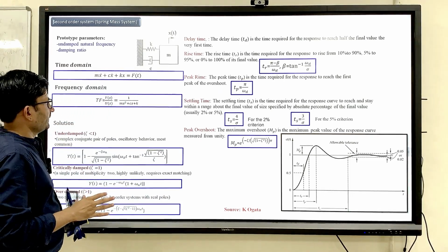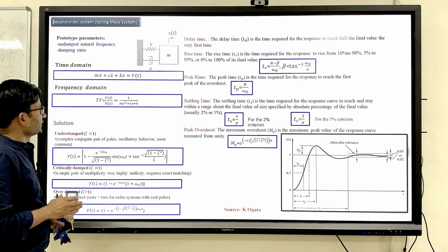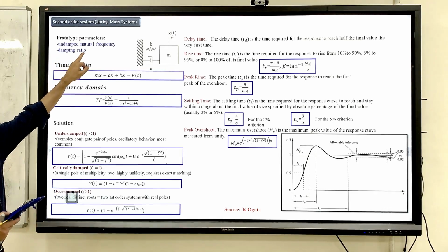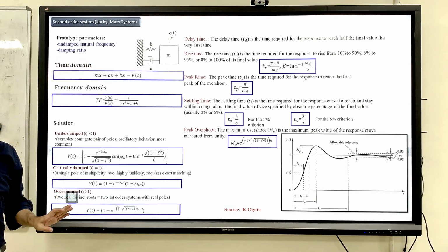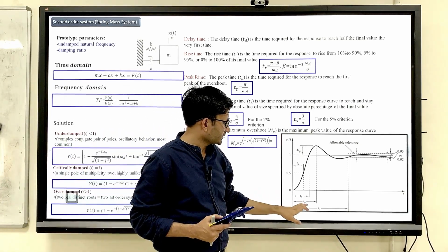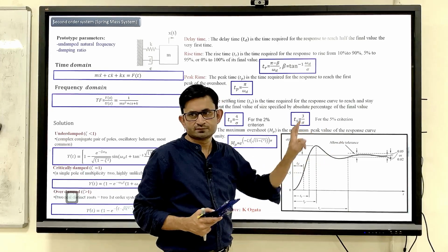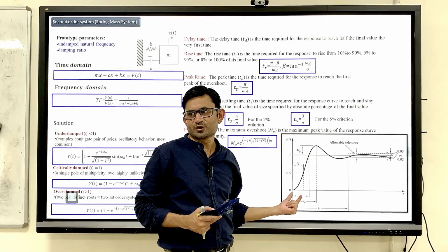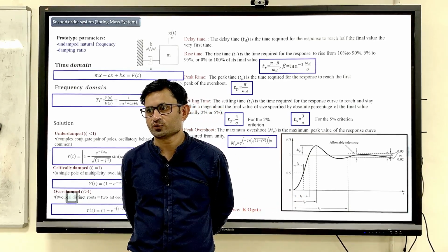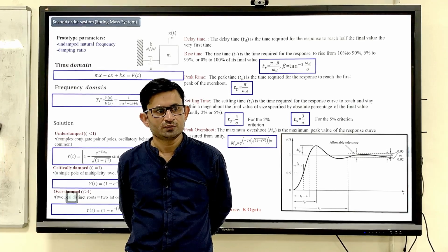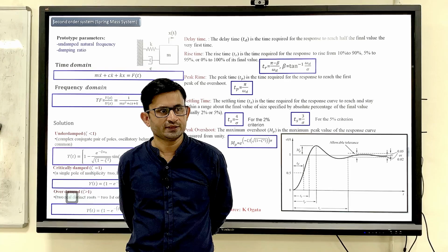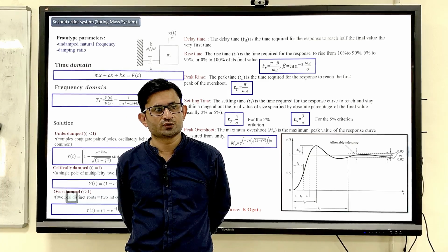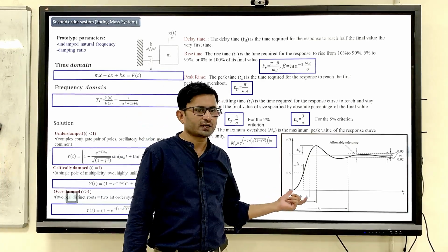So do not worry about each and every thing, I will discuss with you. I will tell you the two parameters: one is natural frequency and another one is the damping ratio. Let's say this is the arbitrary response of any system. And why is it starting from 0? Because in the transfer function, what have you assumed? Zero initial condition, right? So you have to have a feel for that. When you have assumed zero initial condition, that is why your graph is starting from 0.